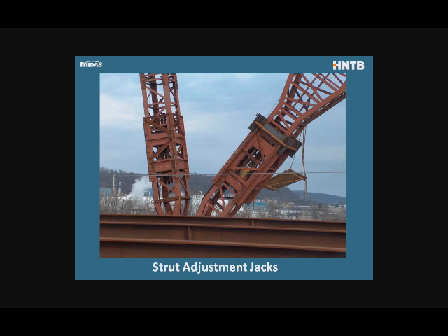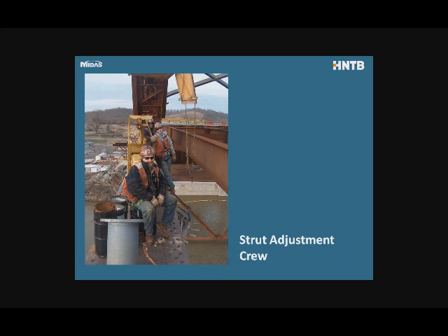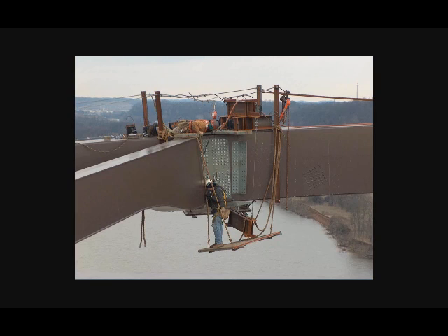And so just by inflating and deflating the jack and adjusting the nuts on the rods, they could adjust the jacks to again a fraction of an inch, 1/8 of an inch, no problem. And here's your friendly strut adjustment group. It's 3 people. The guy in front runs the hydraulic pump, and the 2 guys in the background adjust the nuts.